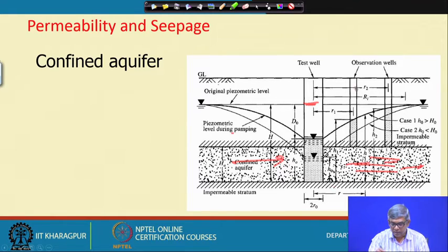So, that means, like the previous case, I can make different observation wells. Initially, if the pump well is here and the observation well is here, then the water level will show at this level everywhere. Now, when I start pumping out, suppose the water level comes here, and then your drawdown will be from like this or like this. If the water goes from this level to beyond this, the equation will be slightly different. I will discuss the water level when it is above this.